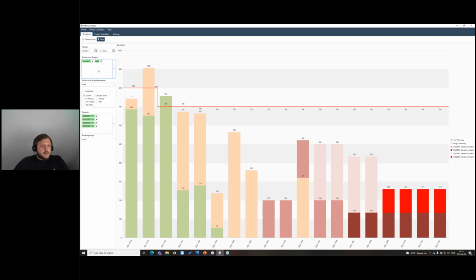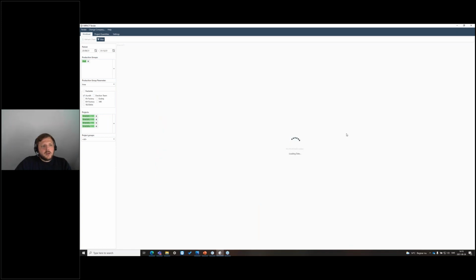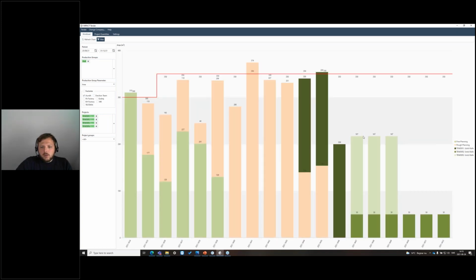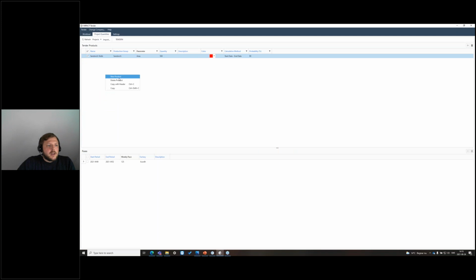So let's continue with the walls. I will do the same. When can I do the walls? Let's see here in my list. So probably I can do it from week 46. I have some room. But here it's suitable to say, okay, I'm gonna start it week 46, and I see that I have a capacity of around 100 to 150 square meters a week. So let's say 130. So I'm gonna put the start date and a pace in this option.